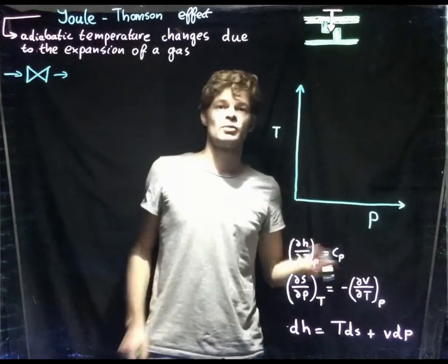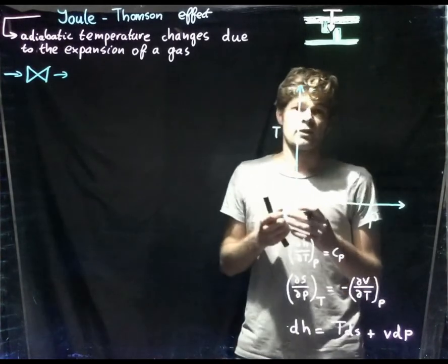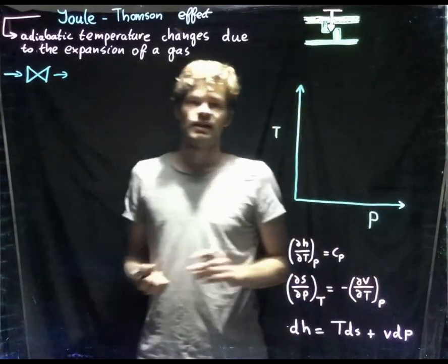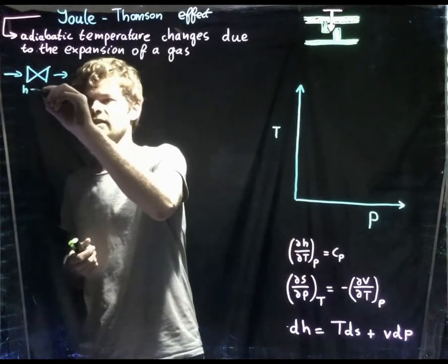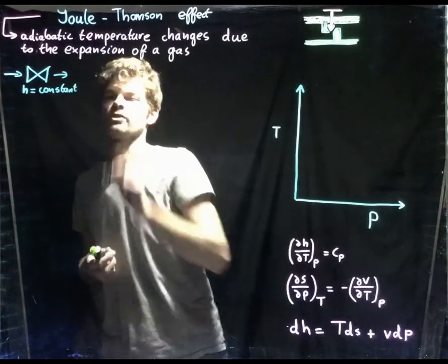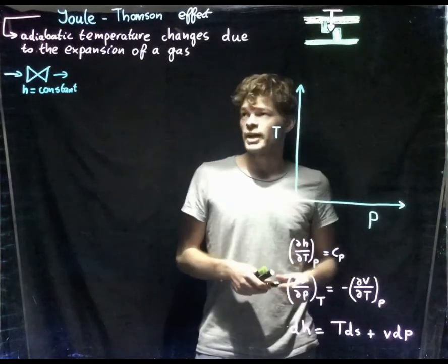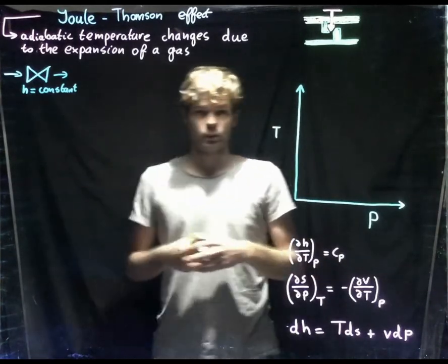it's always assumed to be adiabatic, so there's no energy transfer with the surroundings. And since the flow going in is equal to the flow going out, the enthalpy is constant. So there are no changes of enthalpy. But there are changes in temperature and pressure and velocity and whatever, so we're going into detail with them.